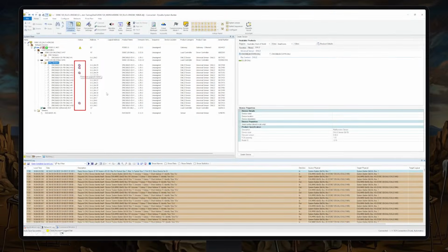One more advantage that we have now is once a firmware upgrade is done, System Builder will highlight the failures if there were any. This makes it easy for future troubleshooting. One important point, as Daniel mentioned earlier: we cannot mix old and new DALI sensors or dry contacts under one universe or under one controller.